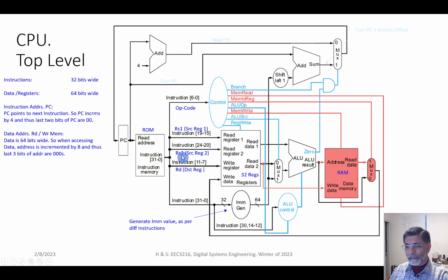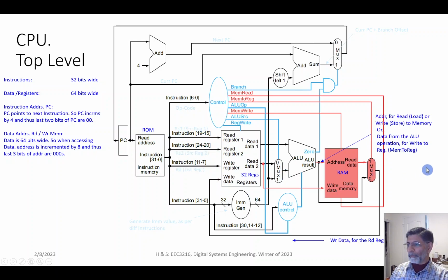subsections, like the address for source register 2 and the address for source register 1, and like you can see, they then go to this array of 32 registers, as RISC-V has 32 regular registers. So these are those registers here. Those addresses would be taken from the 32-bit instruction. So this could also be a type of decoder, along with this decoder here and this decoder here. I'll talk about the decoder in a while. So this is another section of the CPU. So let's go to another one.